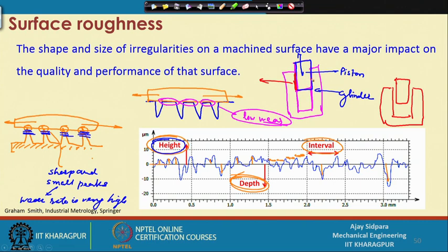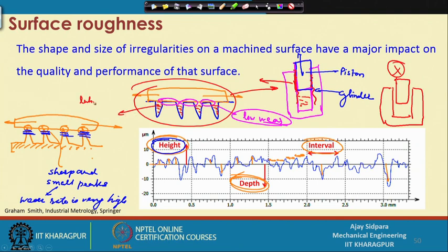Other than that, you always need lubrication, correct. So, when it is moving up and down, you fill this with oil, and this oil will be spread on this surface. And if you use this particular surface here, there are a lot of advantages. One thing is that the contact area is large. Another thing is that these valleys are filled with the oil, so your friction will be very, very low. This pattern will actually have the lubrication retention property.